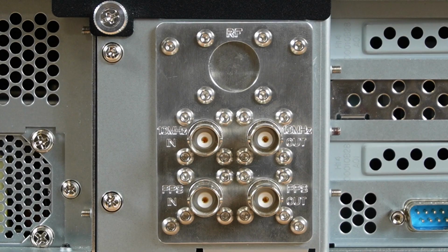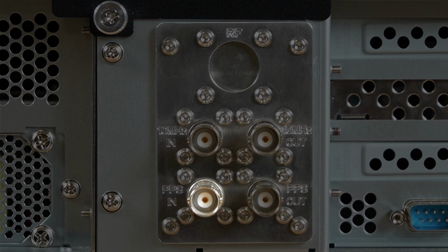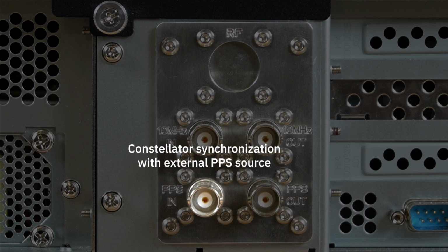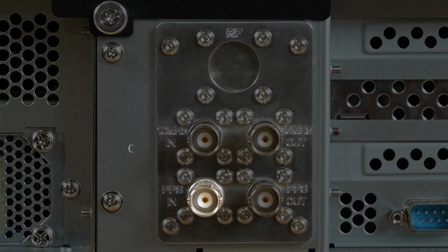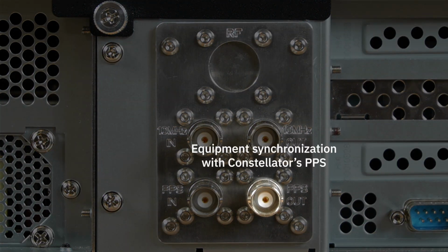The second one, in the top right, is reserved for the internal 10 MHz output. It is used when you want to use the clock of your Constellator as a clock reference for other equipment. The third one, in the bottom left, is reserved for the PPS-in signal, used to synchronize the Constellator with an external PPS source, PPS standing for pulse per second. The fourth one, in the bottom right, is reserved for a PPS out. It's used to synchronize other equipment thanks to the PPS out of the Constellator.